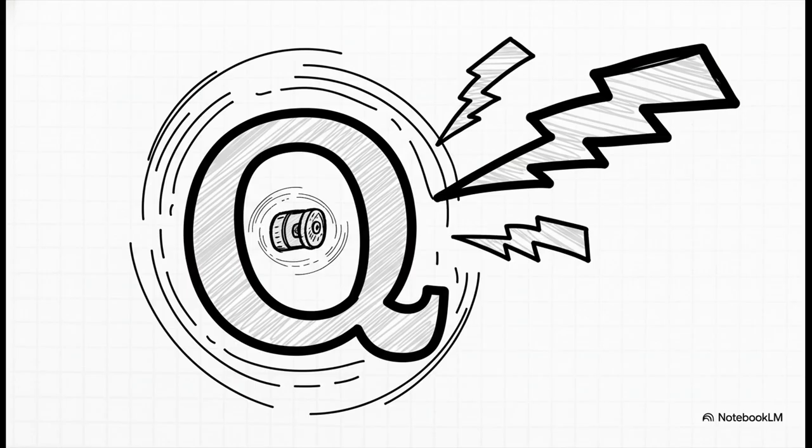And this should feel pretty intuitive from Faraday's law of induction, right? The faster those magnetic field lines are cutting through the stator conductors, the bigger the voltage you're going to induce. So there you have it. The ideal voltage boils down to the machine's construction, the magnetic field strength, and the rotor speed.